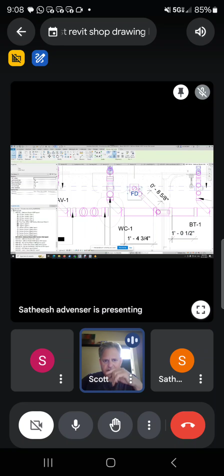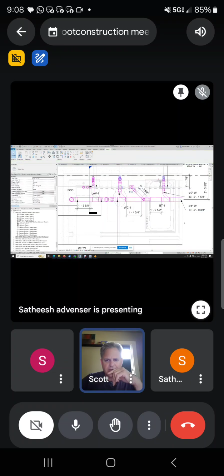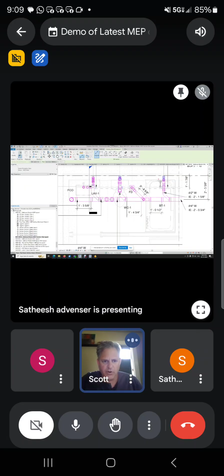And I see that you got a measurement. If you scroll your screen down a little bit, I see that there's a measure to the center line. But really, when we're building the floor, we want to make sure that we drill a hole for that to come up through. If you could give us a cheat, what I'm getting at is almost another view that just shows all the penetrations. Even though you have it here, a less complex view that just shows the penetrations and the size of the penetrations. So where the toilets are and the vents, you could say, hey, we need a 3.5-inch hole right here where the toilet is coming up through both ways.